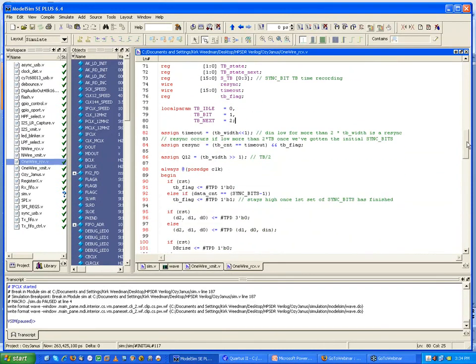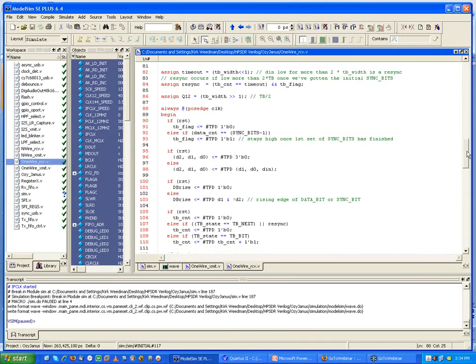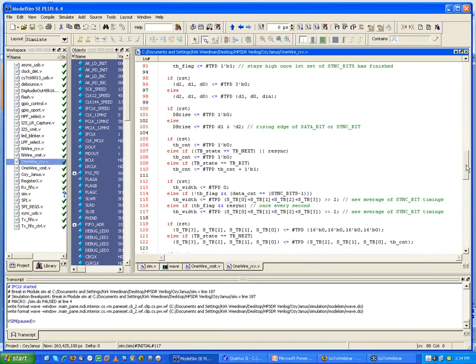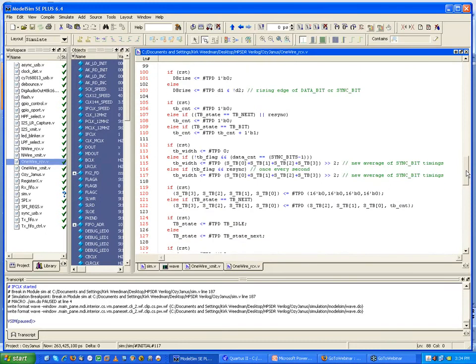So let's go down to the rest of the code here, and in this code you'll see that I have an always block that's running on the positive edge of clock. That's the only controlling event type statement in this always block, and because of the way I've written it, this is RTL code. This is a subset of the Verilog language that can be synthesized. We'll be talking more about that in the upcoming lectures.